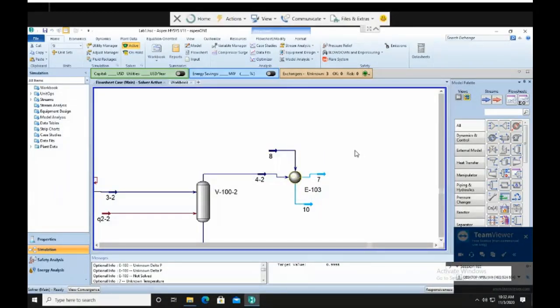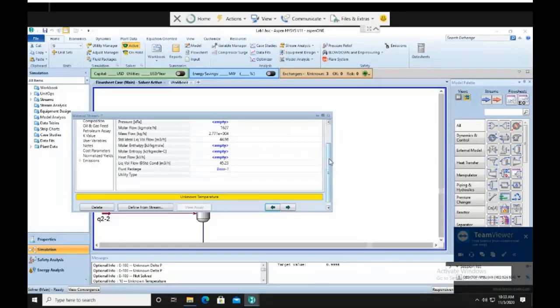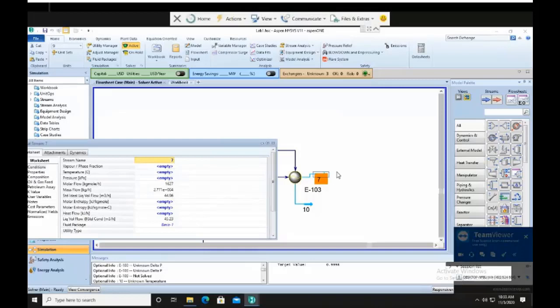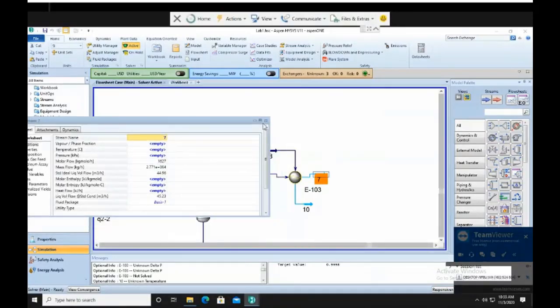Now, set the T out of the tube side to be 10 degrees Celsius, because we want to liquefy this one. So it is wise if you check the saturated temperature of stream 6 before deciding the stop temperature of the liquid product of ammonia. So if you look here, now we want to store this one in liquid phase. So we do not know what the temperature is going to be. Okay. Oh, now before that, we have to put in the pressure inside the heat exchanger.